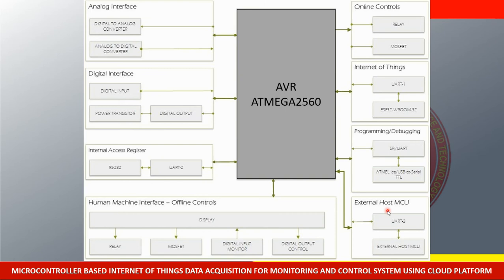Next, for our analog interface, we have the AD5667 and the ADS1115. Both of them have the capability of extracting data up to 4 channels. Actually, the AD5667 is only 2 channels, while the ADS1115 is 4 channels. We will use two. It turns out it doesn't fit exactly with just one. The ADS1115 has 4 channels, the AD5667 has 2 channels, so it would be a waste to leave the extra 2 channels of the ADS1115. And the AD5667 costs only around 200 or 300 pesos. So we will use two AD5667.